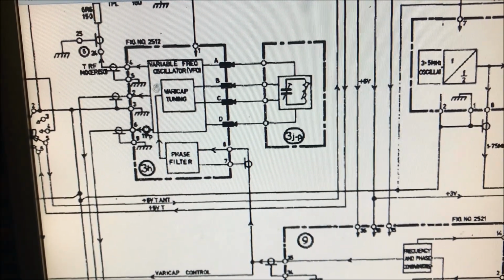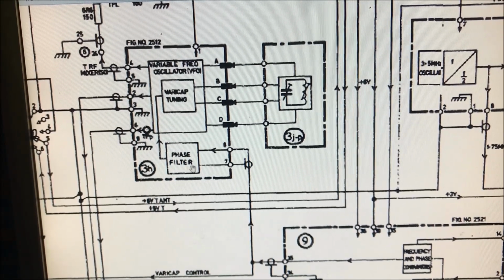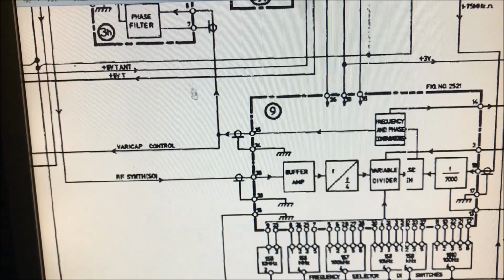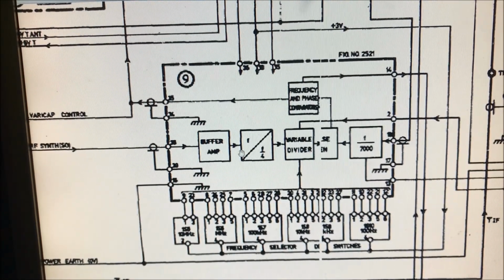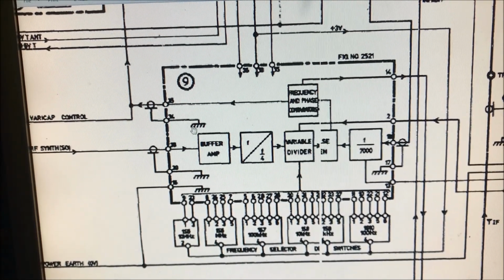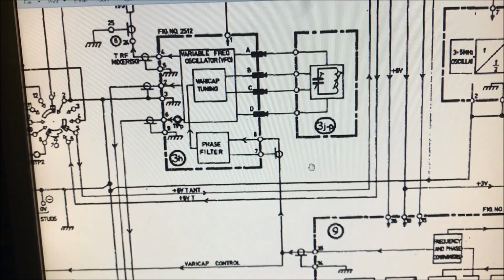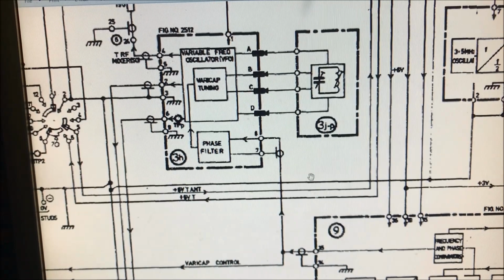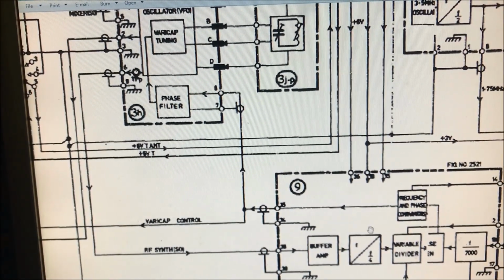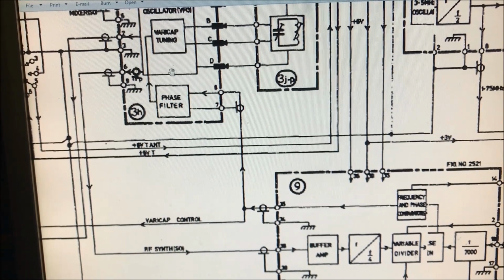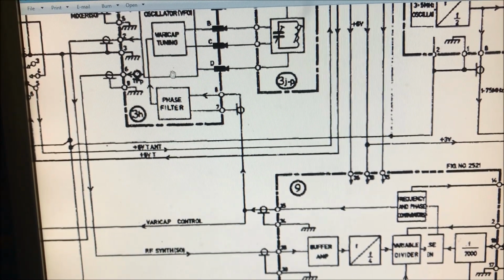It changes it for the transmit and it changes it for the receive. And then that is checked in again by the synthesizer down here, who may decide that it overreacted. So it'll vary the DC voltage again, and the 3H board will react again. So in essence, the wobble in our radio is this thing deciding that this thing here is not doing the right thing and telling it constantly to change.